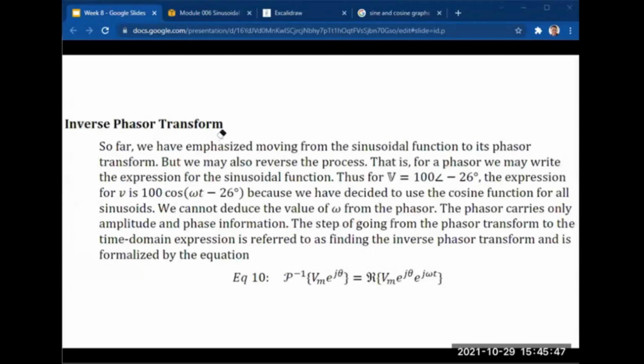So of course, since we can transform our sinusoidal function into Phasor form, we can return our Phasor form to the sinusoidal form. So that is inverse Phasor transform. Okay, the problem here is if we are given the function in polar form, like this for example, we can return it to our sinusoidal function. So again, this is V max.